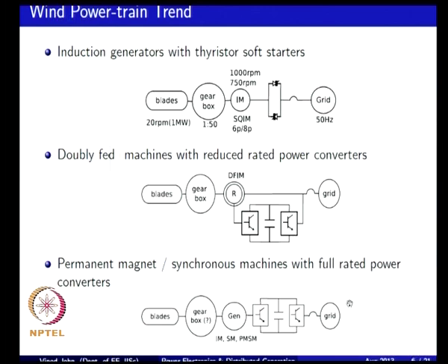many manufacturers as potential turbines that can be installed, especially in the condition when you are having high penetration of wind turbines already in the system and you want to install more turbines, or when you have weak grids where the power that is put out by the turbine can actually cause problems to the grid, then having a fully rated power converter will allow rapid control of power flow, which will help stabilize the grid.